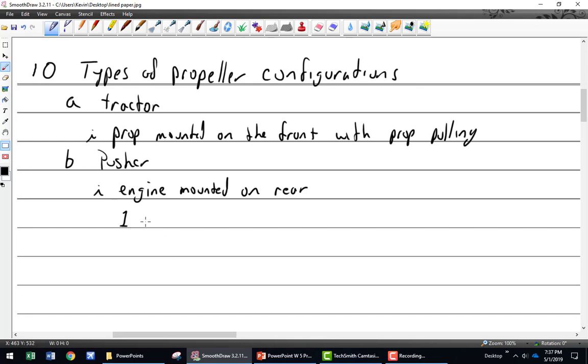Speaking of the Skymaster, and I think it's an airworthiness directive, if you're flying a twin, you're going to grab both handles. You need to go forward on a twin, both engines at the same time. It's a twin, but you don't do that in a Skymaster. You have to lead with the rear engine and get your airspeed with the rear engine, and then bring up the front engine. Anybody care to guess why?